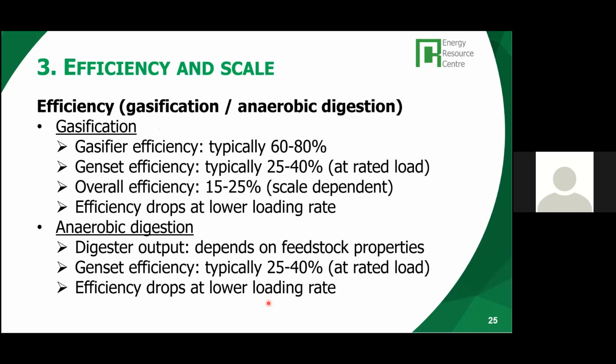Now looking at gasifiers, as indicated, the gasifier itself typically has an efficiency between 60 and 80%. Part of this is also because the gas coming from the gasifier is hot, and it still needs to be cooled down before it can be used in a combustion engine.